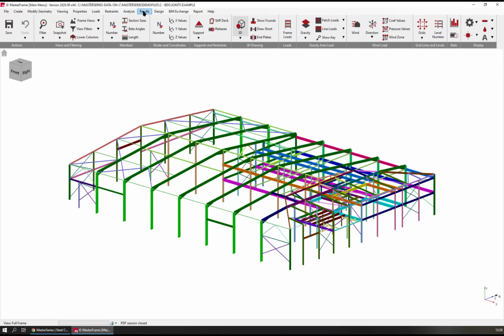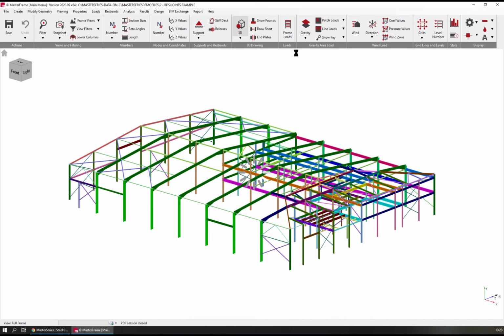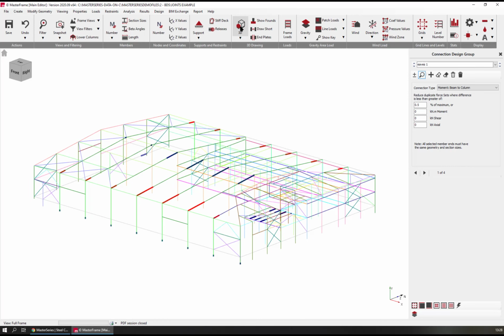And now what I'm going to do is, before I go into design, I'm going to look, yes we are in Eurocode, at something called design groups. When you're doing a frame, you don't want to design the first eaves and then the second eaves and the third eaves. So what I'm going to do, take this down just out of 3D. I'm going to take all of these and put them into the one design group. So all of these rafters are supposedly in the one design group. And then the second one is all of these bases will be in the one design group. Very, very useful.